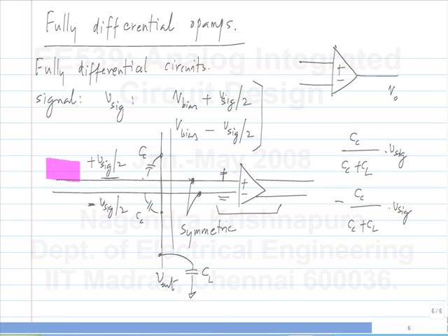Oh yeah. If you have both of these CCs, that's correct. So, because we have a network like this, from V6 we have CC and CL to ground, and we have another capacitor to minus V6. Okay. The exact expression will be CC by 2CC plus CL.